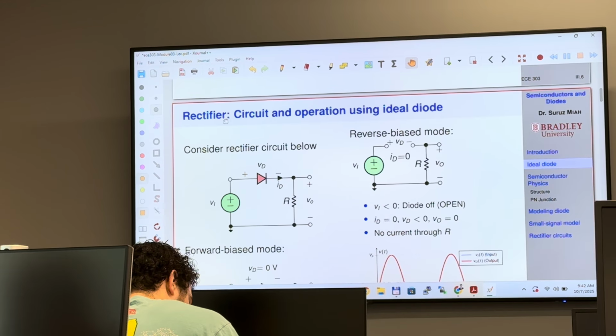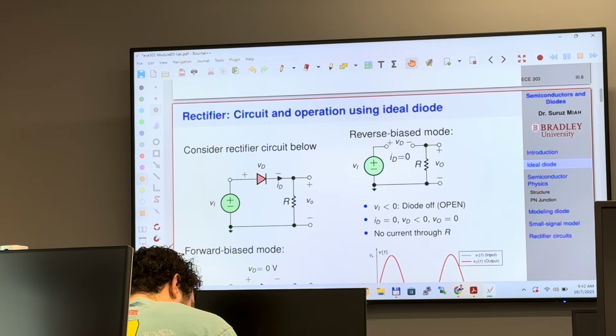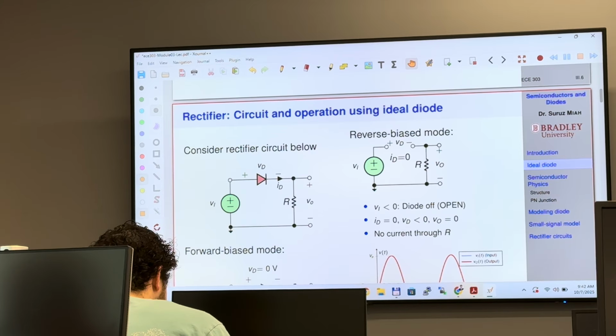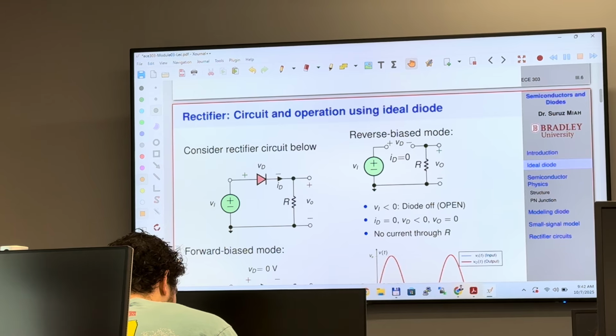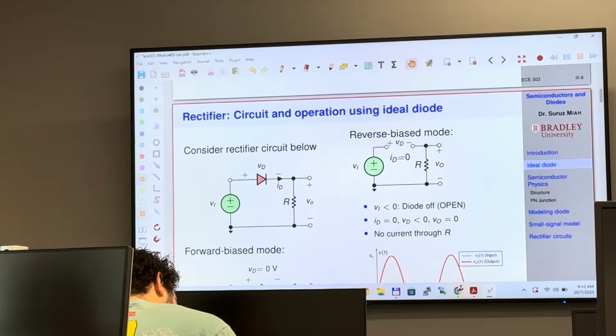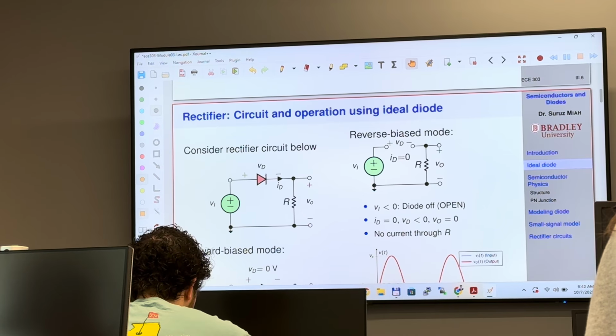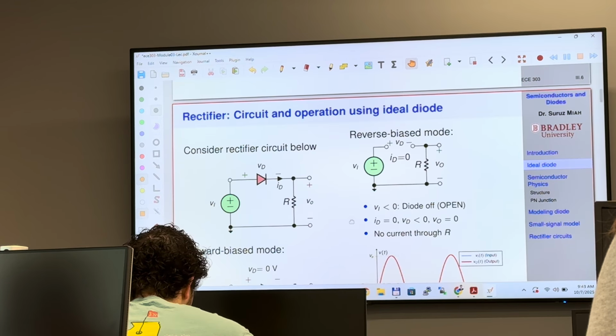And rectifier circuit basically converts the AC to DC. This is the first step of conversion. Of course, like once you have a laptop charger, right? You plug it in, it's 120 volt, it's an AC voltage, but your laptop is taking 12 volt DC. Of course, inside this adapter you have a complex circuit. But how does it do it? This is the first step of converting: the half-wave rectifier. So you see what it does.